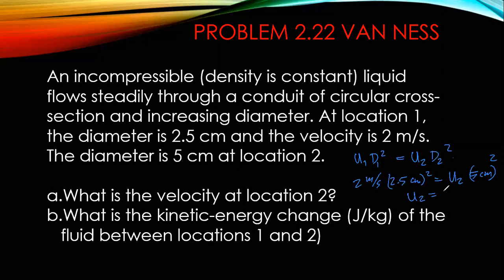So, 2 times 2.5 squared divided by 25. So, 0.5. Are you getting 0.5? Questions? Okay, so the second question is, what is the kinetic energy change in joules per kilogram of the fluid between locations 1 and 2?